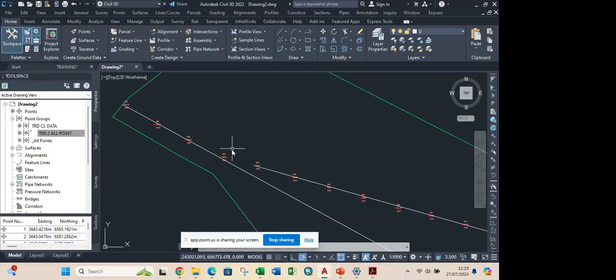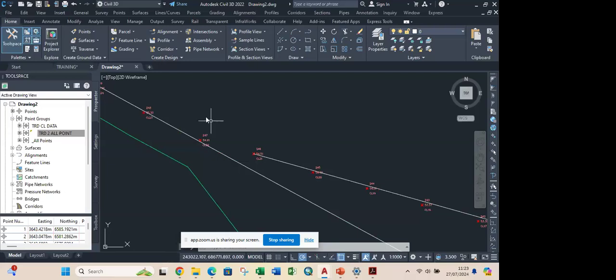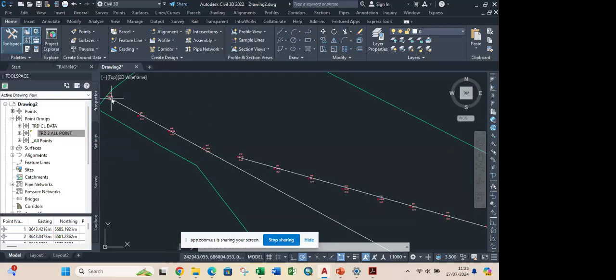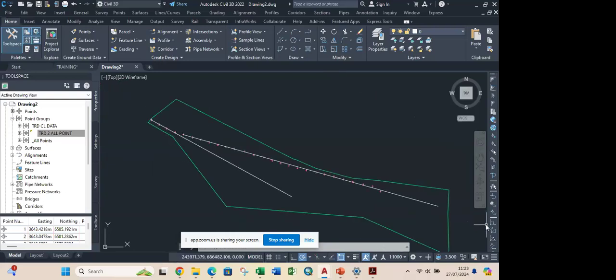I know that at this junction it will likely be a little curve, based on how the terrain goes. That's why, when the surveyor goes to site for a reconnaissance survey or a detailed topographical survey, it's always good for an engineer to be with them, and they will establish those areas that will have critical curves on the road.